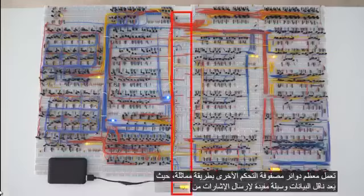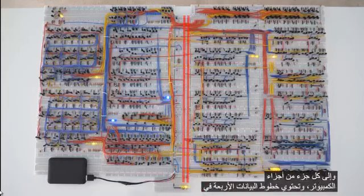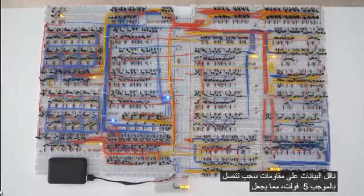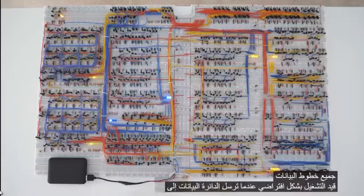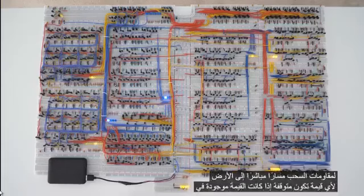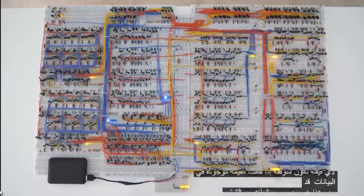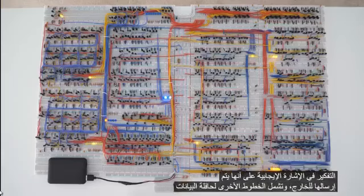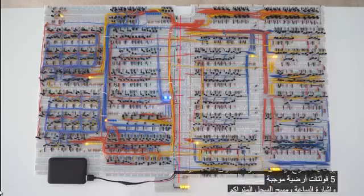The data bus is a useful way for signals to be sent to and from each part of the computer. The 4 data lines of the data bus have pull-up resistors that connect to positive 5 volts. This makes it so that by default, all the data lines are on. When a circuit sends data to the data bus, it is actually providing the pull-up resistors a direct path to ground for any value that is off. If a value is on, the data line just stays on. This might seem counterintuitive, as it is common to think of a positive signal as being sent out. The other lines of the data bus include ground, positive 5 volts, the clock signal, and clear.